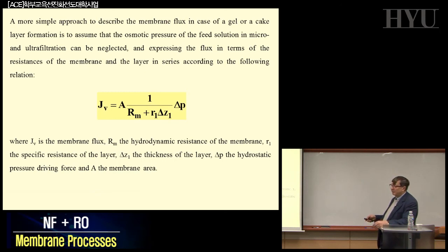The membrane has an intrinsic resistance that you can measure in water from the slope of your plot, but with time you can induce additional resistance to the initial one. This can be related to the formation of a certain deposit, or a gel, of a certain thickness, and that is a layer additional to the membrane thickness that characterized the membrane resistance at the beginning.